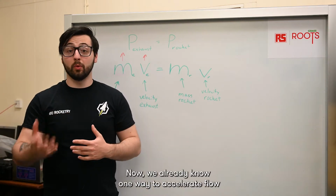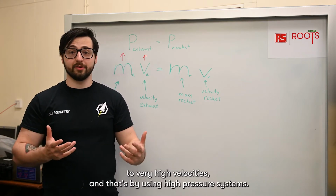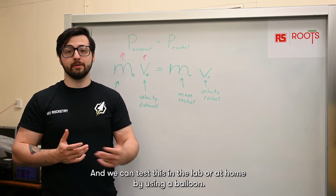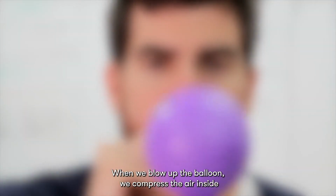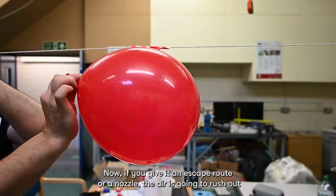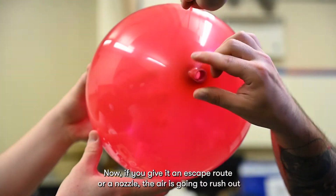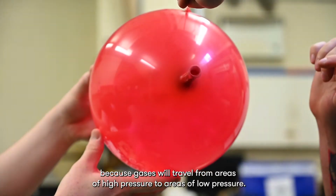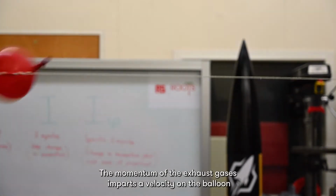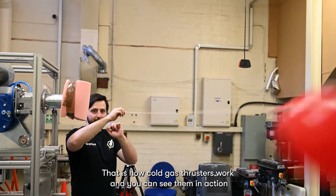Now, we already know of one way to accelerate flow to very high velocities, and that's by using high pressure systems. And we can test this in the lab or at home by using a balloon. When we blow up the balloon, we compress the air inside and can see it pushing against the walls of the balloon. Now, if you give it an escape route or a nozzle, the air is going to rush out because gases will travel from areas of high pressure to areas of low pressure. And the momentum of the exhaust gases imparts a velocity on the balloon, giving us thrust.